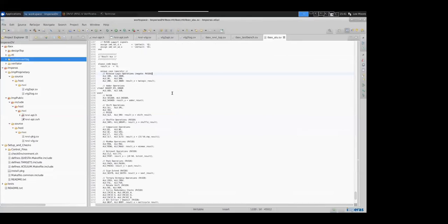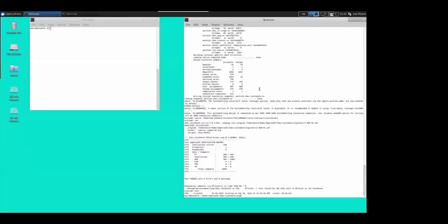And so where I'm going to do this is in the ALU. You'll see here in this ALU, we put in a hash define or a tick define, in terms of Verilog speak, for something to corrupt the behavior of the ALU add in the ALU sub function. And we can enable or disable this through our command line to exclude this bit of the code. Now, of course, the example I have here is running the ALU compliance test. So if I introduce a corruption here, I'm pretty hopeful that the compliance test should find this.